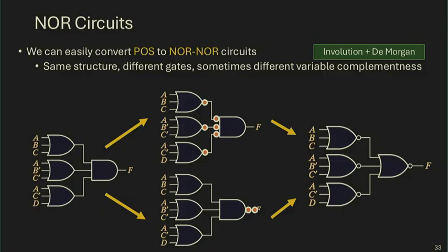So we talked about two-level SOP or POS, and here's how we convert each of them to the corresponding NAND or NOR-only circuit. And remember, product of sums can only be implemented in this NOR-only format. Sum of products will translate into a NAND format. There's no easy way to switch between them. You cannot use NOR gates to easily implement SOP, simply because when you do bubble pushing, this is what you'll naturally get. If you want to get everything to be a NAND gate, you have to do a lot of transformations. Bubble pushing doesn't naturally give you a NAND-only circuit for this POS.